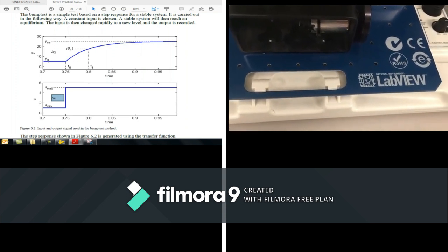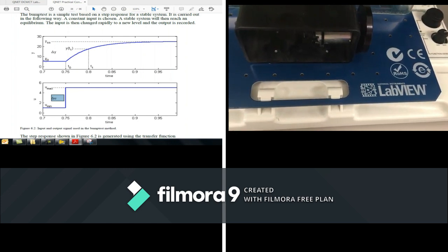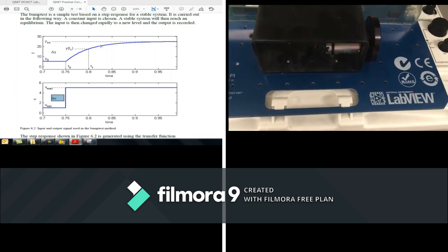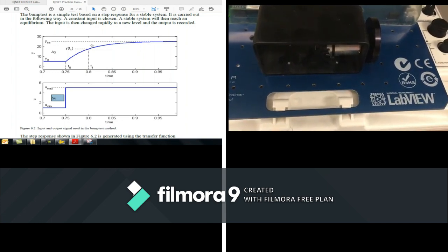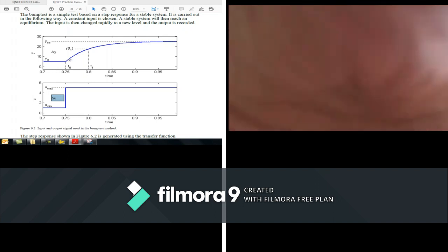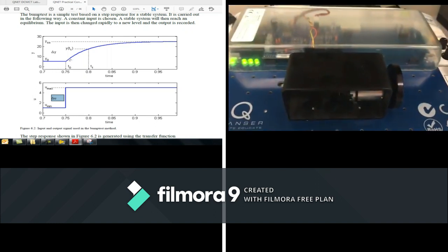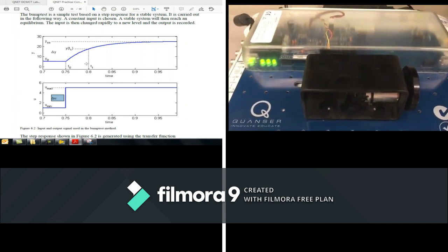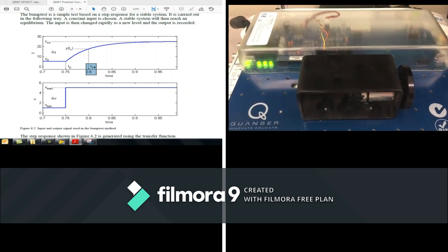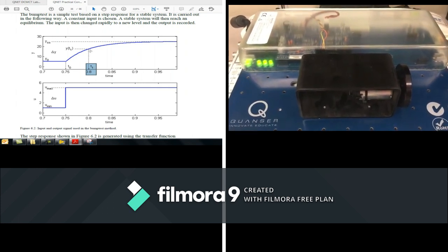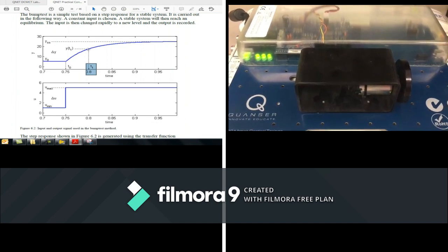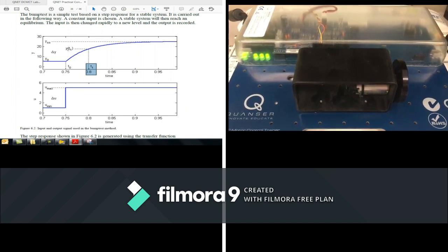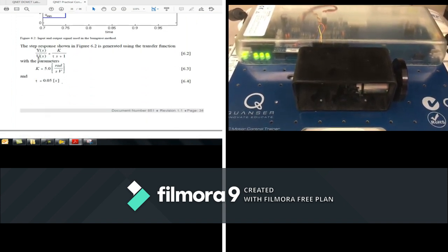At the same time, we have our initial Y, the initial output, Y0, which is initial speed in our case, and then gradually it moves into the steady state Y, the steady state output. I'm sorry, I slipped. So we know that the time constant is the time needed to reach 63%. So this time will represent the 63%. We have the formula in here.